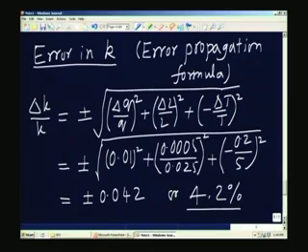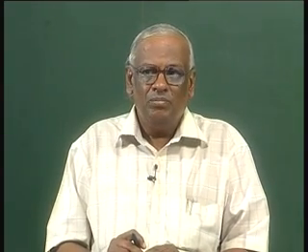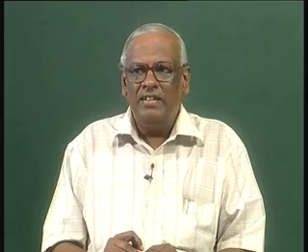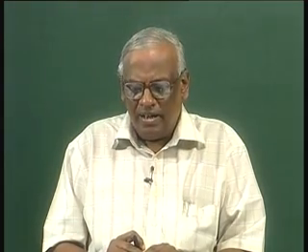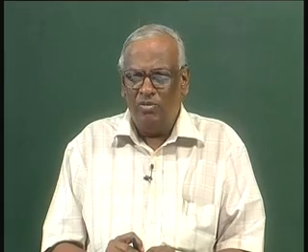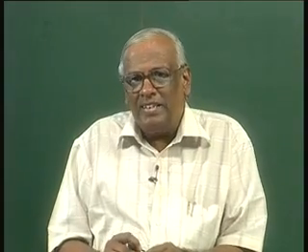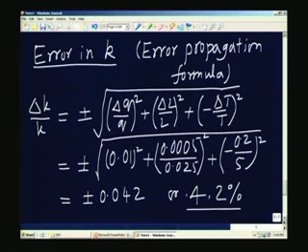This is a very typical value of error when you use a guarded hot plate apparatus. According to the normal standards specified for the guarded hot plate apparatus, about plus or minus 5% is the expected uncertainty in the value of the measured thermal conductivity, and in this particular example it is within that plus or minus 5%. So, we can say this is plus or minus 4.2%. In fact, I can now specify the value of the thermal conductivity of the solid as 0.4 plus or minus 4.2%.